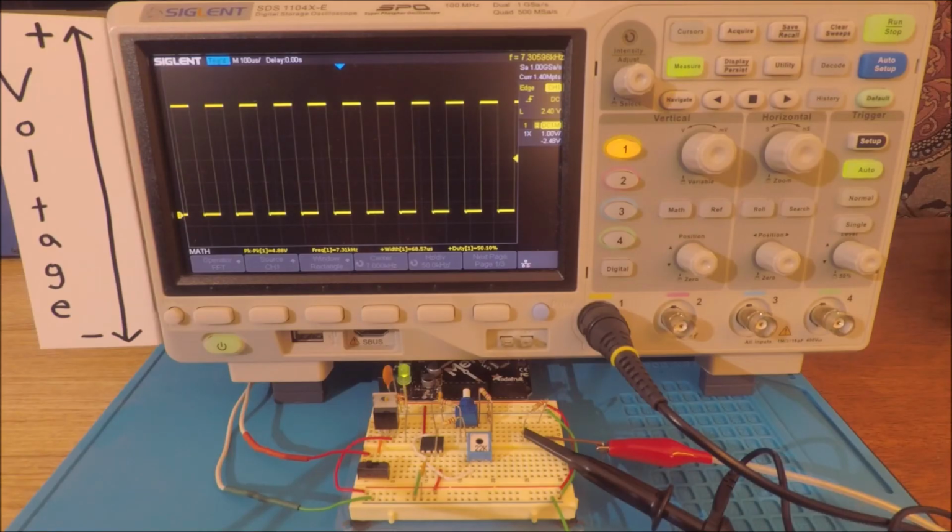Back to our waveform display on the oscilloscope. The screen is telling us that this waveform has a frequency of 7.3 kilohertz and a duty cycle of 50%. Thereby, we're creating a very nice square wave. And so now we understand that we can construct this wave from our fundamental sinusoidal frequency that would match 7.3 kilohertz, as well as the summation of all the odd order harmonics at increasing frequencies. It would be great if we're able to view these harmonics directly in the frequency domain.